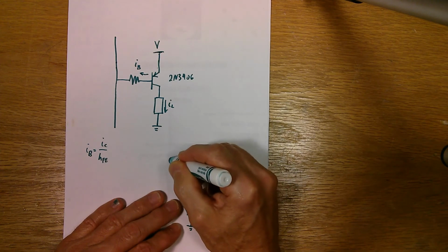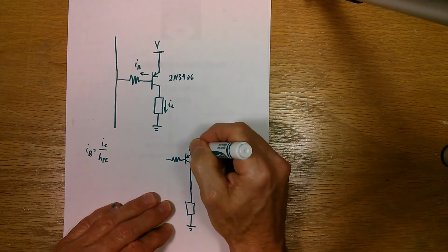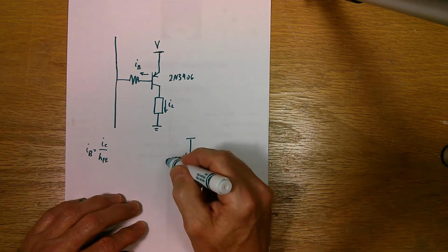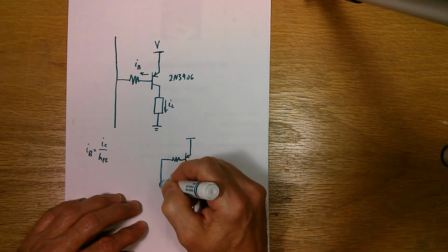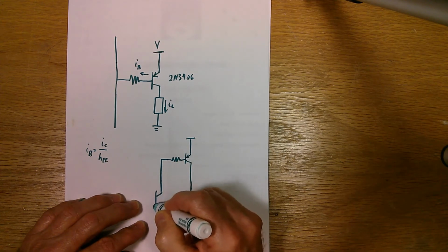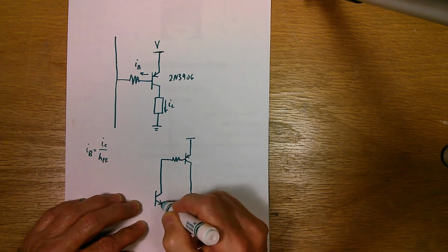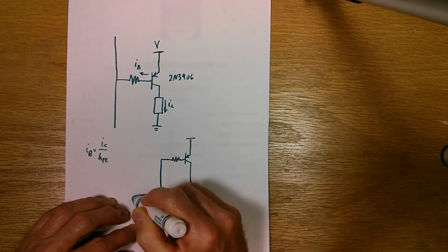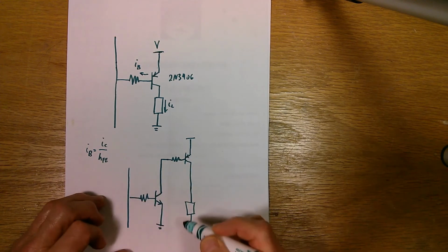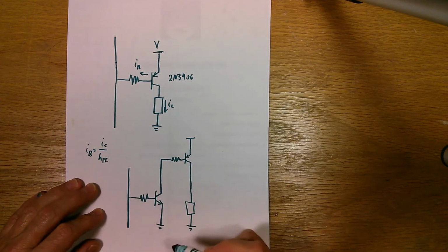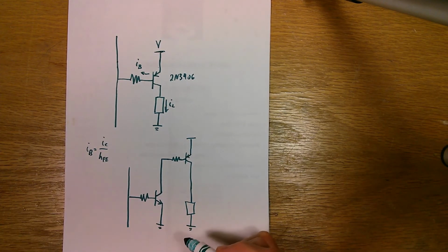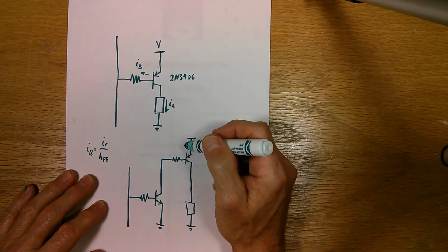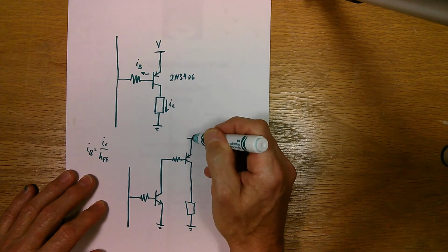We need a base current limiting resistor in the PNP base. Now we can hook up another transistor down here. This time it's an NPN and it goes to ground. Another base limiting resistor, and that one goes to the microcontroller. And we need another resistor here just to make sure that this transistor turns off.